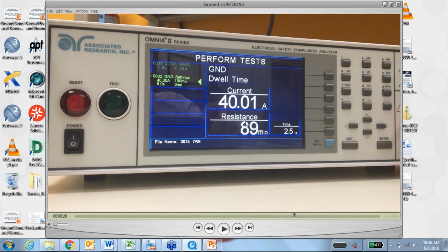If I was the company that produced these soldering irons and I see my resistance is near 89, what I would want to do to create uniformity within my products is set my high limit, keep it at 100, which is what the standard calls out, and maybe make my low limit 80. Because if I'm not hitting my low limit, that means the input wire on this DUT is different from the one I've been seeing on the previously tested DUTs.